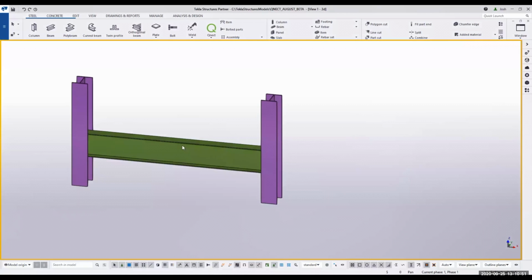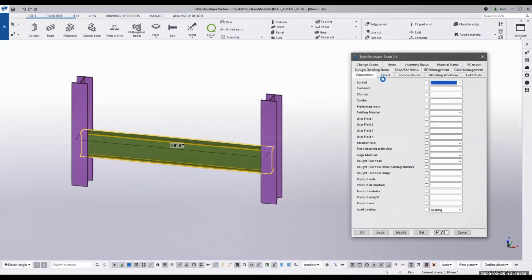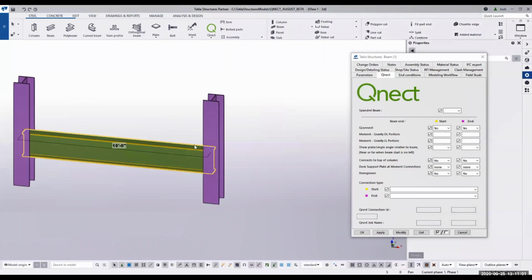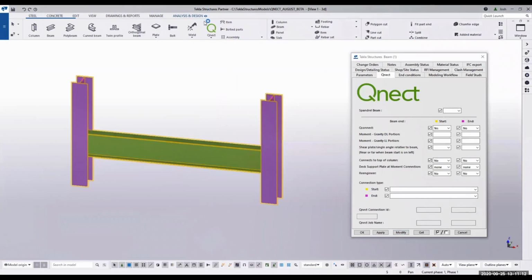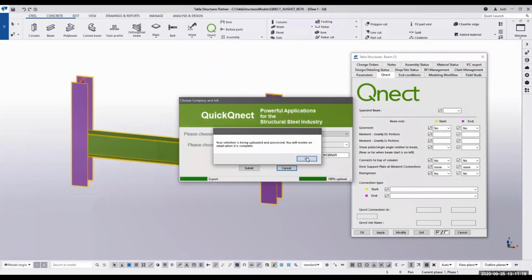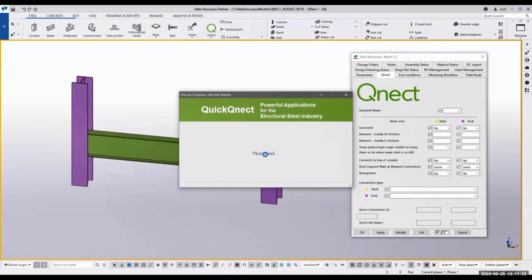Okay, let's look at the beam end 1 and end 2 UDA updates. We'll go to the user defined fields, go to the QConnect tab. First one we're going to look at is going to be QConnect, which we're going to say no to the end location. So the goal for this is if we have specific connections, maybe they're one-off or something we are told has to be done outside of the realm of QConnect. Well, we know we're not going to connect there, so we're going to tell the system just that. No, we do not want to connect.